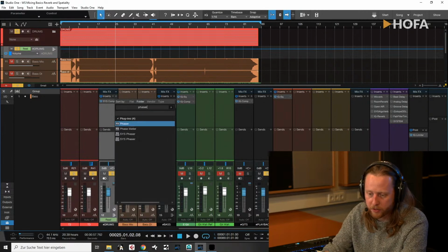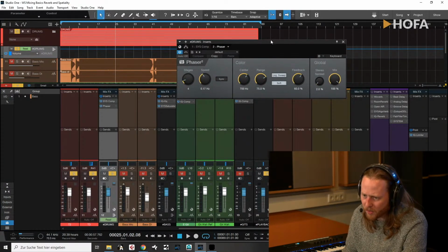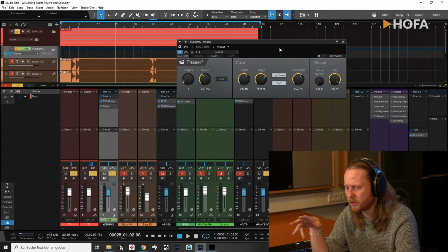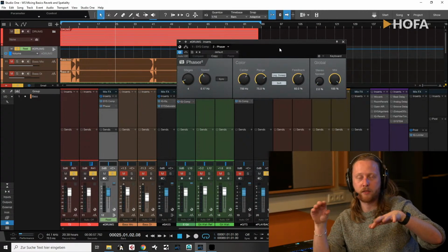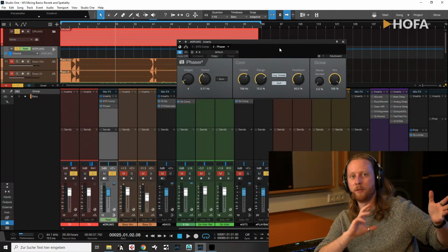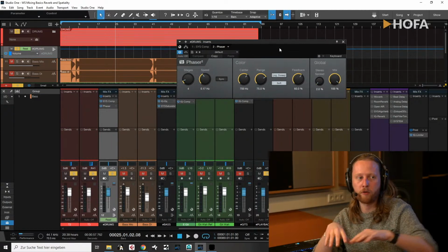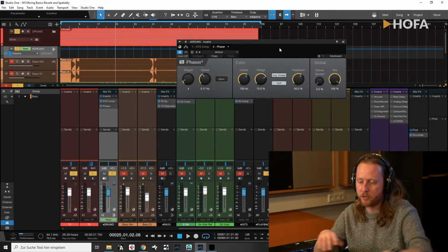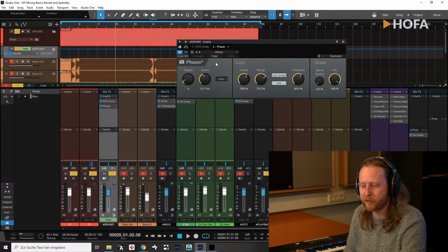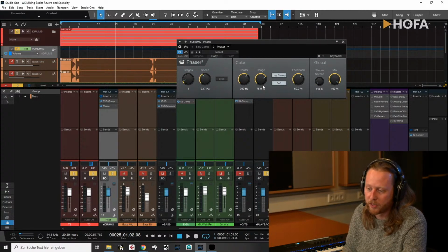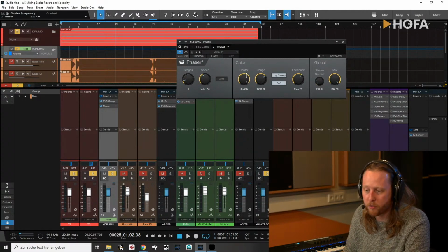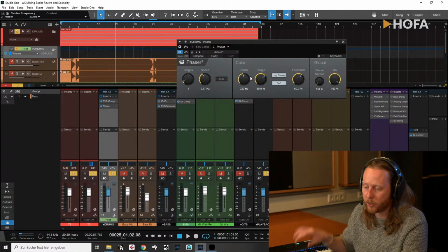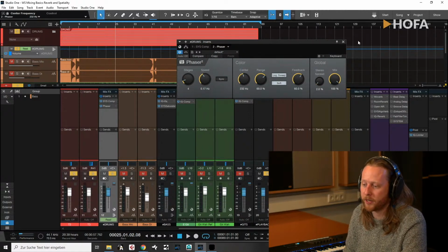There's another one which is very, very similar to that. Real quick, this is the phaser. Technically seen, this is not a delay here. It's an all-pass filter, so we don't have exactly the same delay amount or phase shift amount on each frequency. It's different and frequency dependent, so it's a slightly different effect, but basically the same idea behind it. You have LFO speed. In this particular instance, you have not only feedback, but also a color in the feedback, which is basically an EQ in the feedback chain. But other than that, basically the same thing.